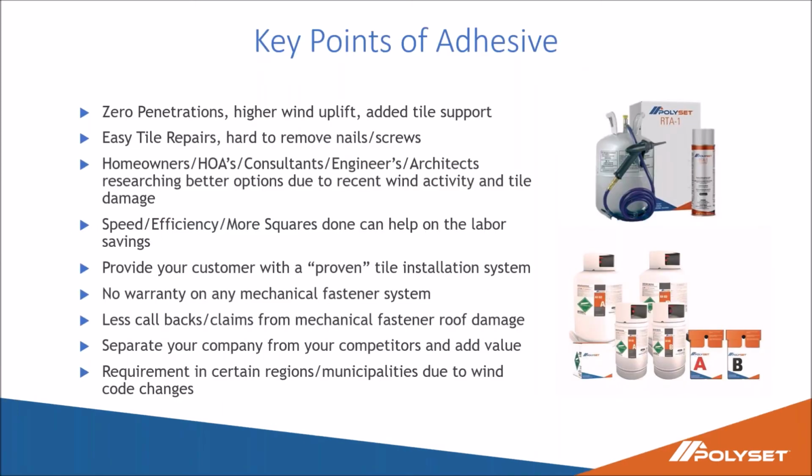To sum up the presentation, here's a couple key points to take away. Again, 0 penetrations, higher wind uplift, added tile support, makes for easy tile repairs, especially when it comes to installing cut pieces. Cut pieces are hard to adhere to a deck. If they're not attached with some type of caulking or adhesive product, you want to make sure that the adhesive manufacturers provide that proper training to your installers.